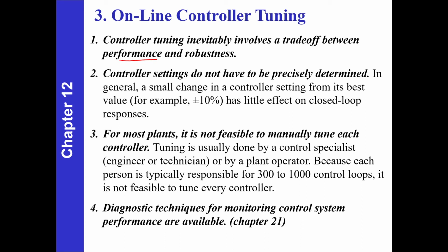Okay, we come back. So, the controller setting, which is KC, tau I, and tau D, it does not need to be very precise, no need to be until 4 decimal places. That doesn't mean precisely determined. It's enough when we get the response that we want.